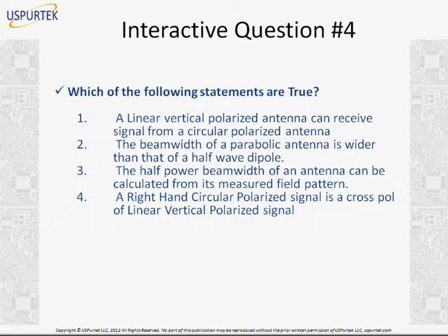Well, there is a question, then why use linear? Well, linear because, of course, it's a matter of implementation. Of course, there are benefits for having circularly polarized antennas, but that will add to the cost of your handset, the cost of your base station. To keep things more practical and commercially deployed, we use linear antennas mostly. But you definitely have a good point here.